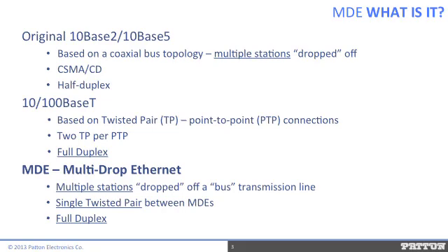In other words, multiple devices could access the same medium, but only when it sensed that no other devices were transmitting. Because collisions could occur, retransmissions would be necessary, but not necessarily successful. Ethernet is therefore a non-deterministic protocol, which means there's no guarantee that the transmission would be successful. Deterministic protocols guarantee successful transmission.